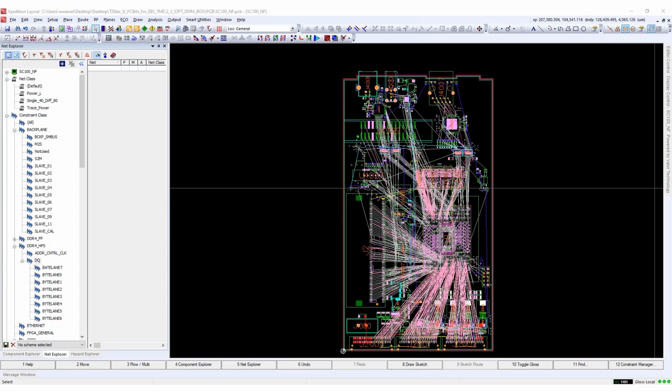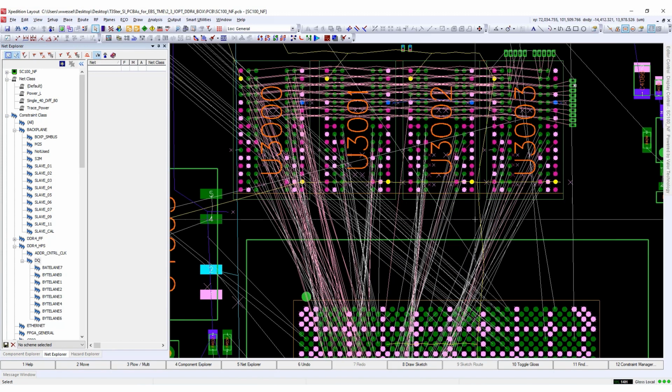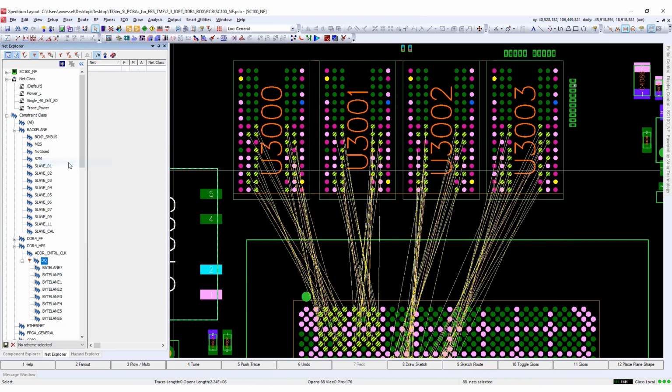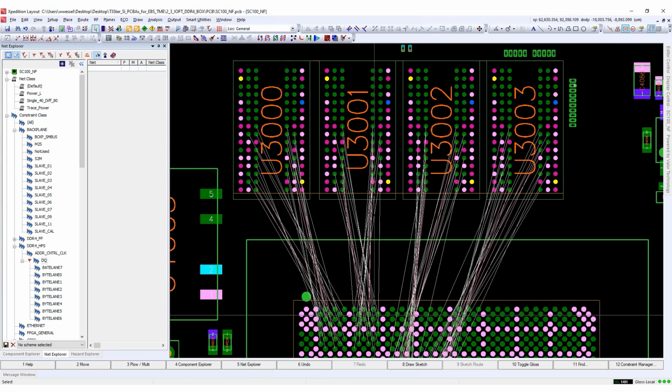Based on the component placement, I want to pre-optimize the FPGA pin assignment to reduce the breakout and fanout effort. These steps help us to identify channels much easier and allow us to make good design decisions about routing layers and sorting of signals. Netline filtering helps me to define a strategy up front, and I can set the focus on critical nets like the DDR4 data and strobe signals. In addition to that, it is easier for me to review changes in the pin assignments later.